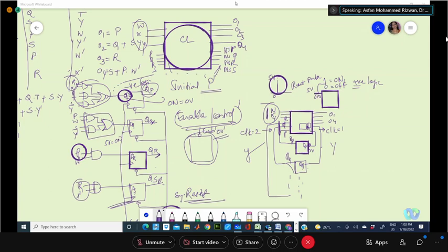You need to have a counter. Practically, there will be a sensor placed at one intersection point, either at the entrance or outside. At every intersection in one direction, we'll be trying to count up. The sensor placed outside the door will be an incoming counter. The sensor placed inside the door will be a down counter. That sensor pulse will be taken as a counter input, and that counter output will be taken as the digitized form. You'll be taking that as count up or count down.